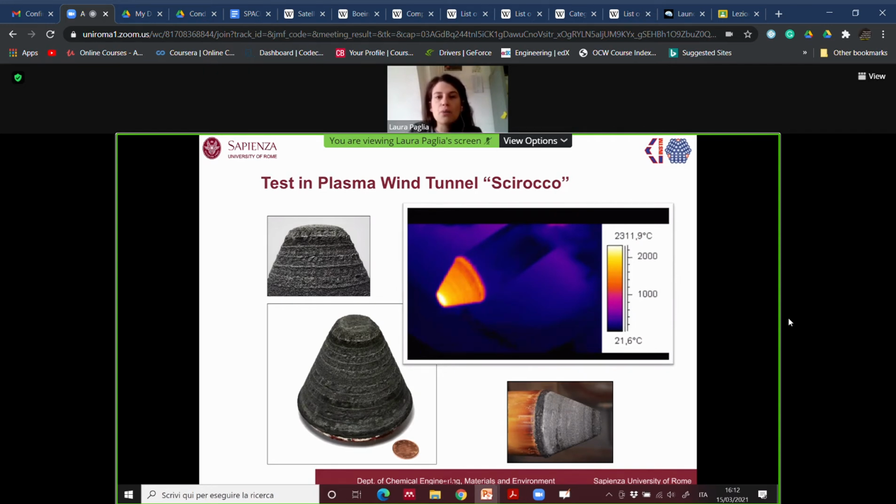Okay. With this setup, we also evaluated the temperature on the surface of the material and on the bottom of the material. Usually there are some pyrometers which are able to evaluate the temperature on the surface of the material, and then some K thermocouples which are able to detect temperatures up to 1300 degrees. So they were the optimum choice for this kind of application.